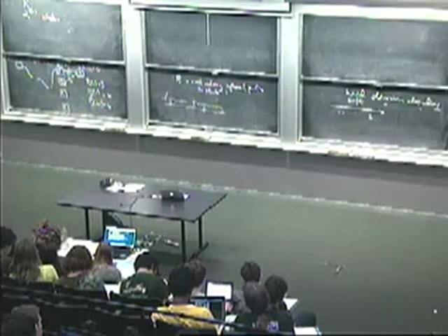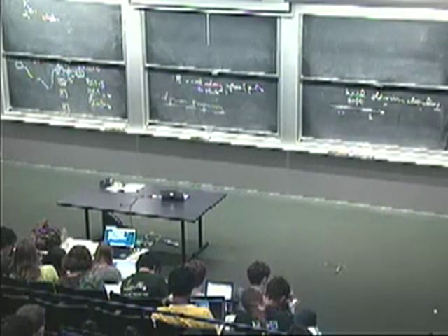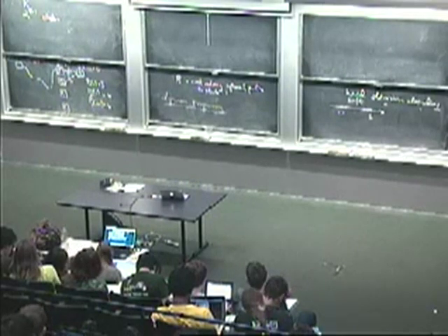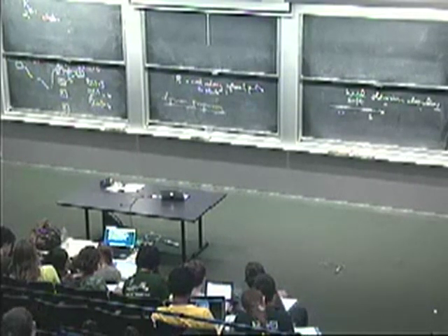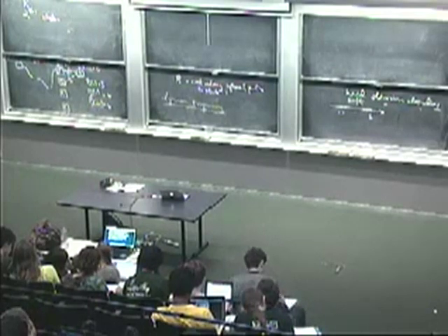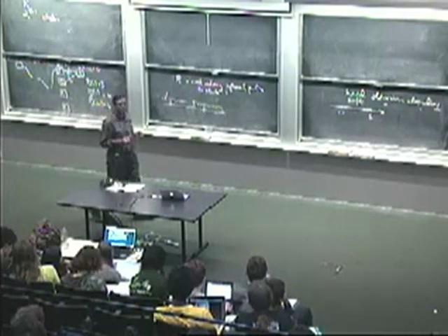So the total Hamming distance between the bits you emit along the way and the bits that you've received is made up of the Hamming distance between the branch here and the piece you've received here, plus the Hamming distance on the branch here, plus the Hamming distance between the branch here and the received segment over there, and so on. So the total Hamming distance is made up of the sum of the Hamming distances along the way.